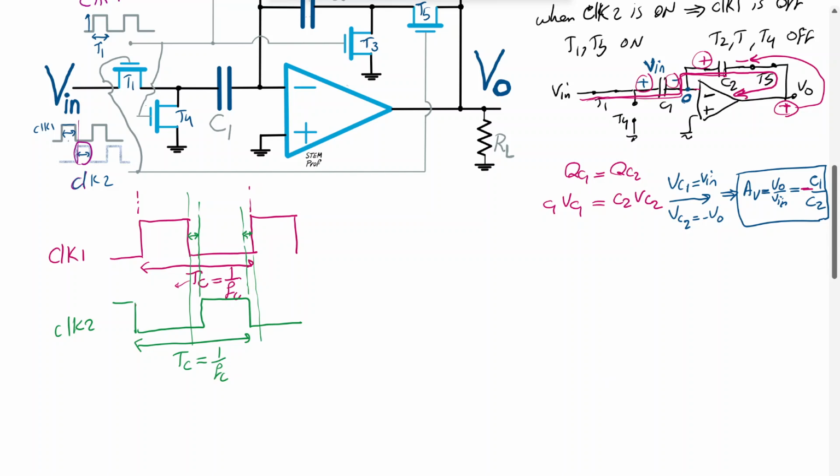Okay, so during one period of the clock, the Vin feels as if the total amount of current that it provides is the amount of current that it provides to charge C1 up to Vin across its plates. So it's as if we would say average current, or basically the current observed in one period, which is always repeated, is equal to the charge transferred to cap C1 divided by the time of averaging, which is the period of the clock.